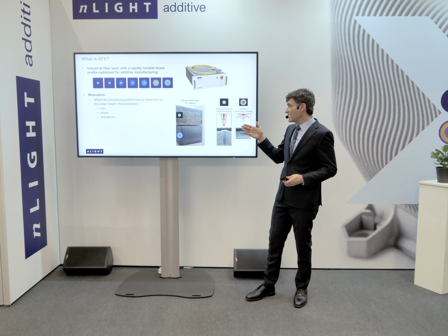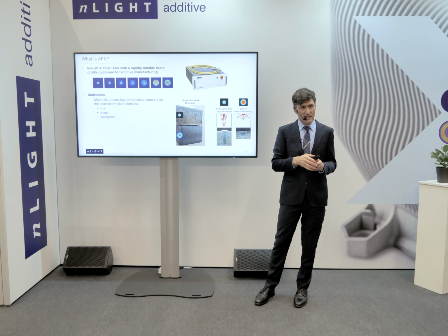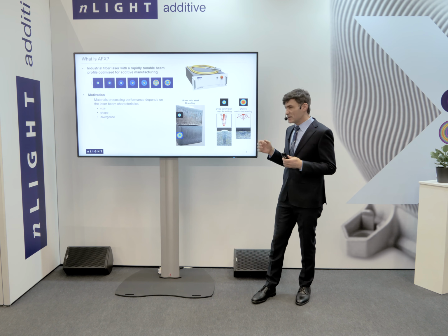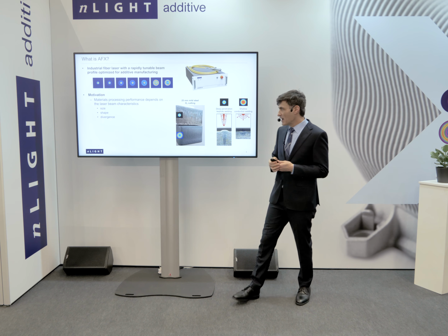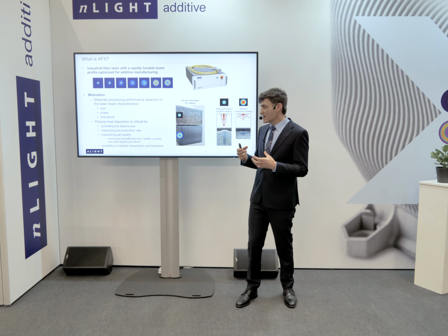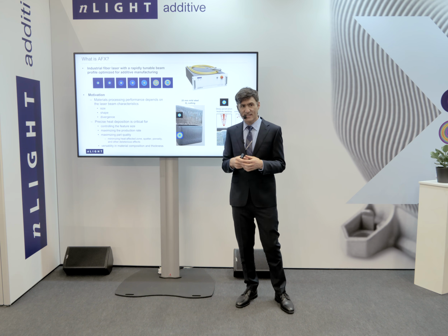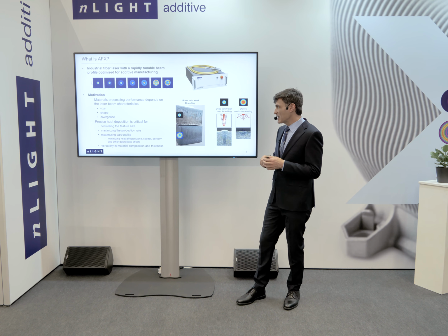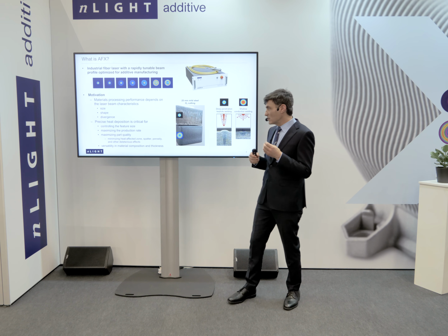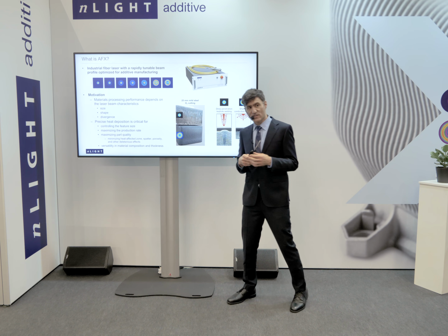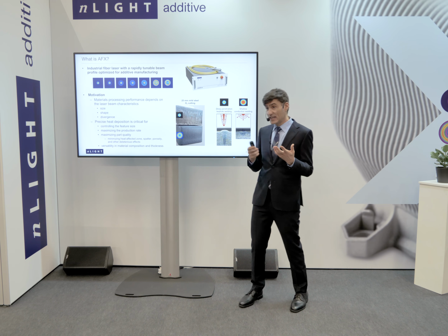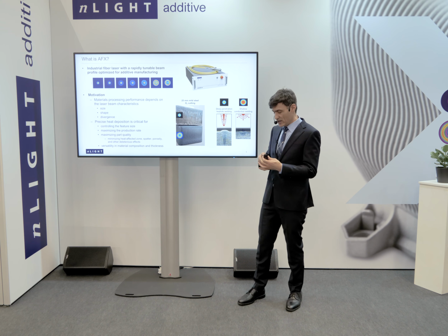Similarly, in welding, it's known that a small beam gives you a deep penetration keyhole weld, whereas a larger beam will give you a more shallow conduction weld, which could be desirable for aesthetic or quality reasons. What's going on here, of course, is that the material processing performance depends on how the heat is deposited into the sample, and that in turn is affected by the beam characteristics. And so to precisely control the heat deposition is necessary for controlling the feature size, for maximizing the production rate, for maximizing part quality, and also for versatility for different materials and thicknesses as shown here.